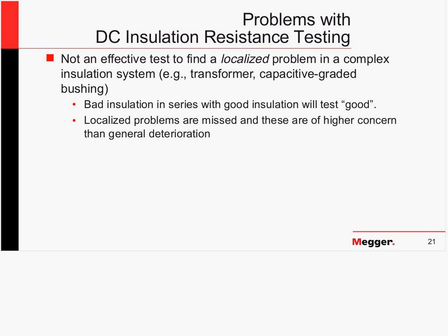So those are problems you want to react to immediately versus, hey, if my whole insulation system's aging and there's general deterioration, yeah, I care about that, and at some point I'm going to react to that. But that's more a situation that you can monitor with time. You don't have to react to it immediately. A localized condition is a high concern.